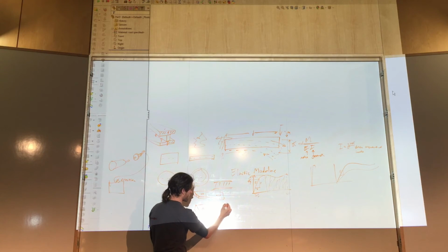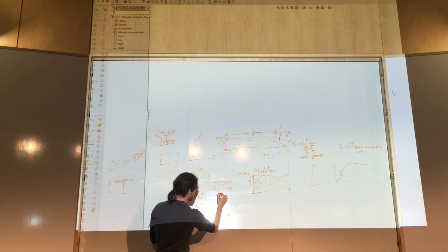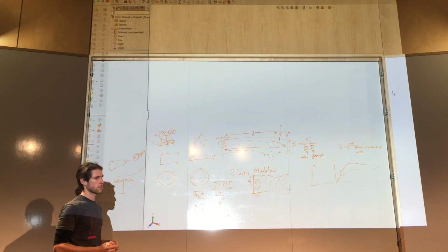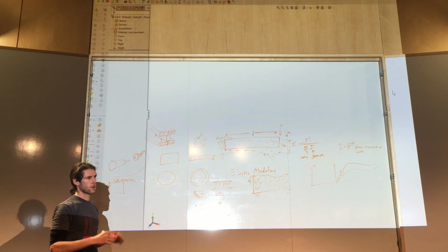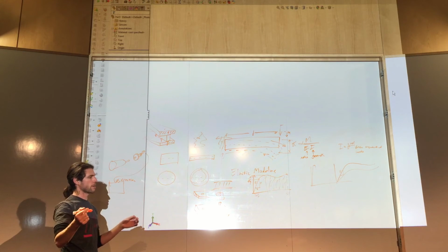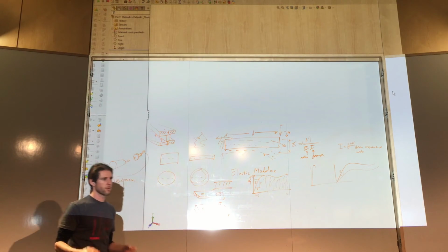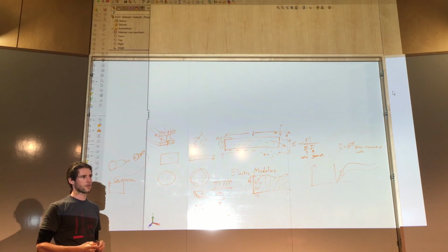You can put that pin over here somewhere, and make sure you line up that slot to match the constraints you're actually trying to withstand. You kind of need to draw out where your variation may be, and then allow some compliance in there, either just a hole, or if you build something, some flexure.